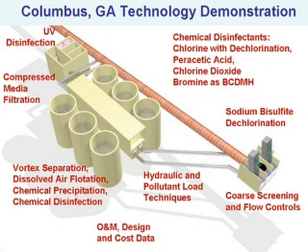And the demonstration would then be to show that these 2 discharges, the treated flow, which would be most all of the rainfall events, and then the untreated or undisinfected flow into the river would in fact meet the bacteria standards. And I'm going to go through what they put in, and then later on in this presentation, I'll show you how they concluded that they in fact do meet water quality standards, and they have demonstrated that there's no reasonable potential to cause or contribute to a bacteria standard exceedance.